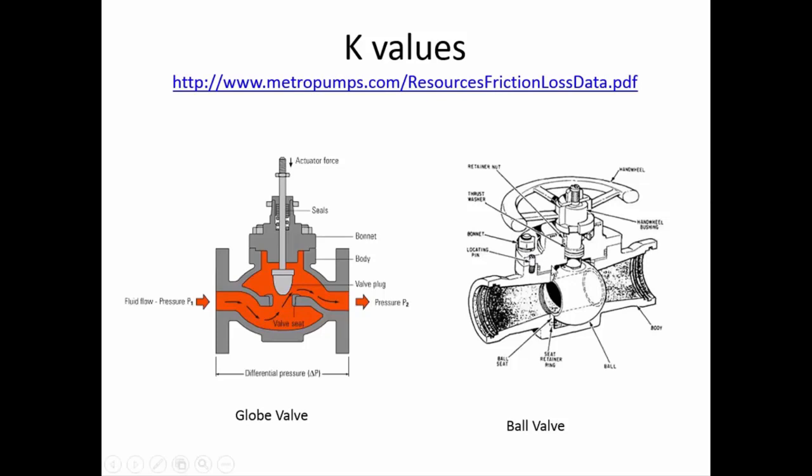A ball valve is really easy to open and close. What you're essentially doing is you've got a pipe section drilled through a sphere, and when you turn the top handle here, you're just moving that hollowed out pipe section from the sphere out of the flow direction, so that the water that's coming in is just running into the leftover metal or plastic in that ball valve. But it can leak around the sides. Water at really high pressures can easily leak around the side of the ball, so it wouldn't be a really great option if you have high pressure coming through the flow.